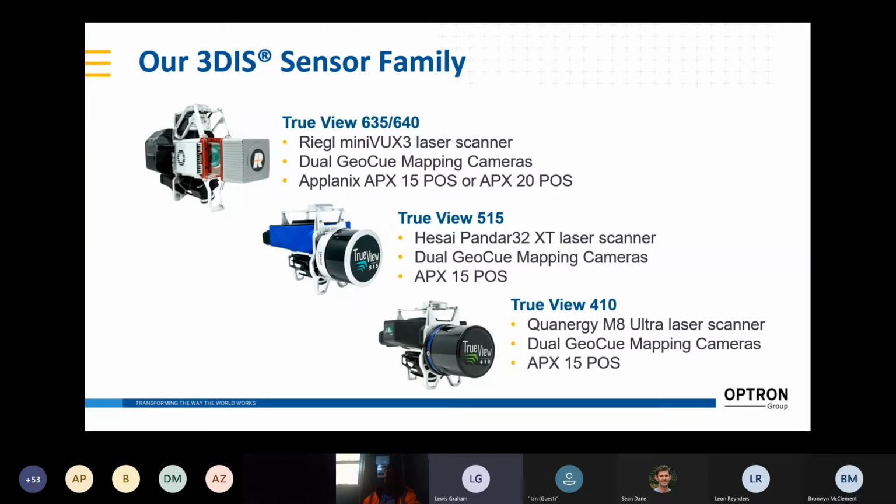Even to this day, Riegl is still the only mainstream LiDAR company that is building LiDAR specifically for drones. Optech has recently introduced a sensor to the market. We've started to evaluate it, but right now the standard for survey grade DOT type accuracy is the Riegl class. And we offer that with 2 different positioning systems, and I'll go into that in a minute as well.